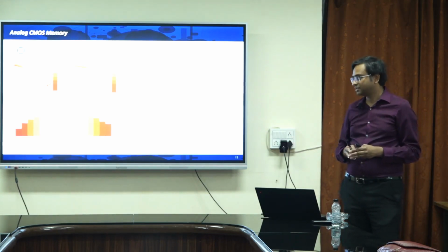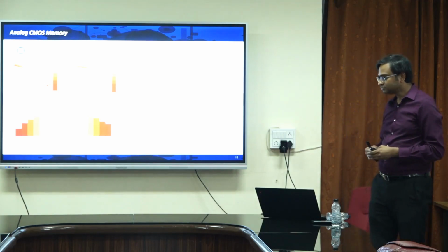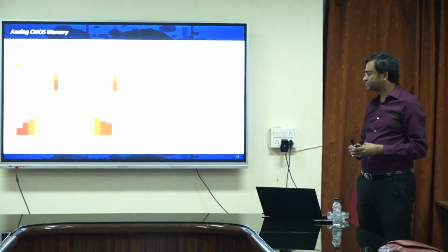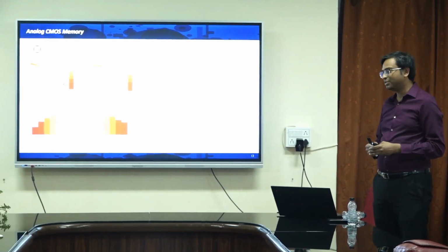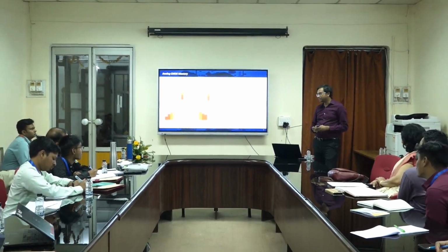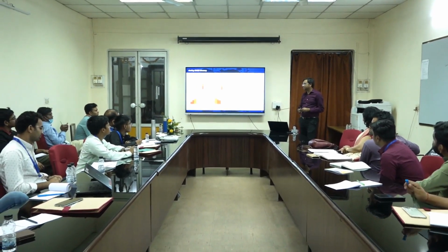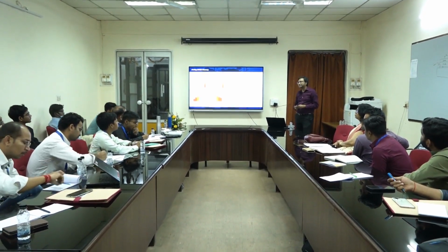Yes. You have used MoS2, right? Now it's depending on the thickness, it changes from N type to P type, right? No. MoS2 remains mostly N type. Making a P type MoS2 is very difficult. Tungsten selenide you can get N and P, but MoS2 you cannot. There is not much thickness dependence of MoS2.